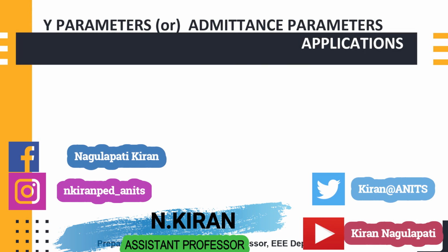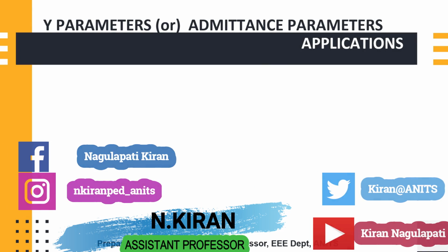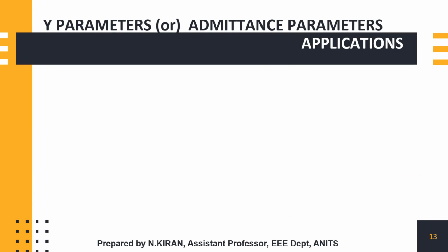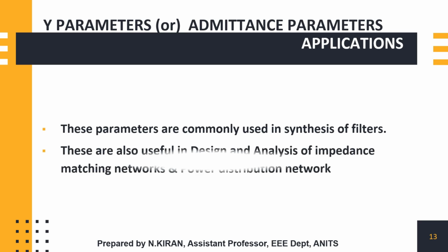Next is the Y parameters or admittance parameters. These also find the same application as in Z parameters. That is, these are commonly used in synthesis of filters, also used in design analysis of impedance matching networks, as well as power distribution networks.